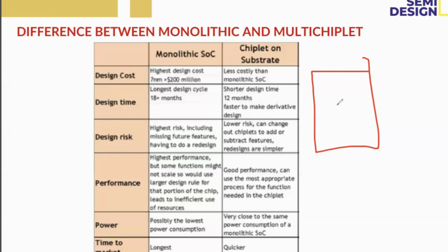Okay, so how will we design the core? Based on which instruction set will we be using for the RISC processor? We are using ISA. What is ISA? ISA means instruction set architecture. It has its own instructions, like I type instructions, R type, register type, jump type, and branch type instructions, right? So those instruction sets we are using for RISC-V.